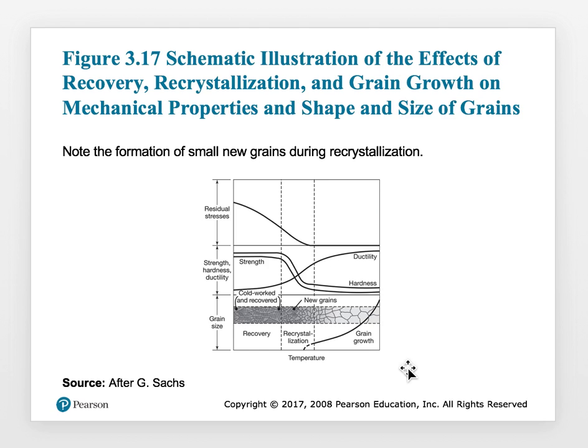They will all start combining and becoming a large grain, and then they will all start recrystallizing into smaller grains or slightly larger grains. And then if you keep continuing to heat up that block of material, you are going to be creating larger and larger grains. So this one schematically shows all the process as you are heating the block of material after doing the cold rolling.